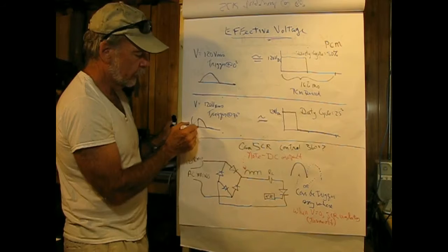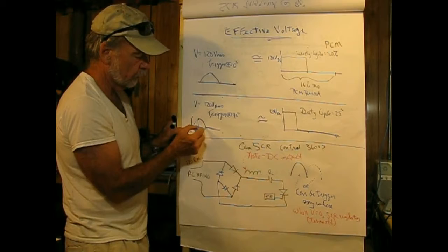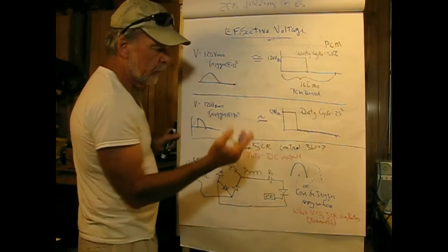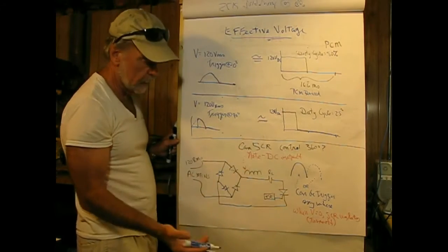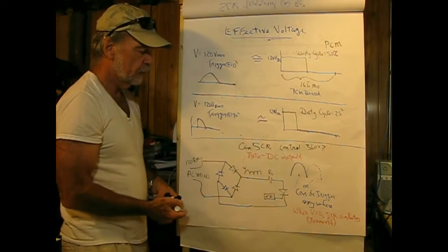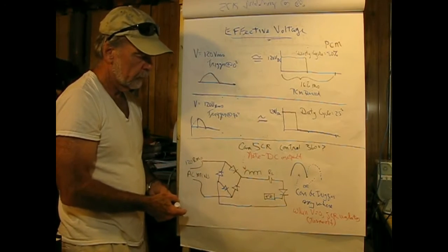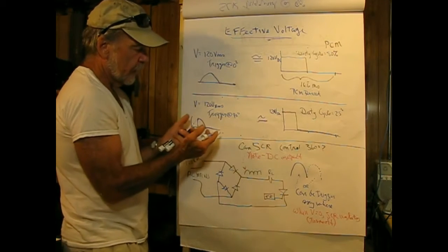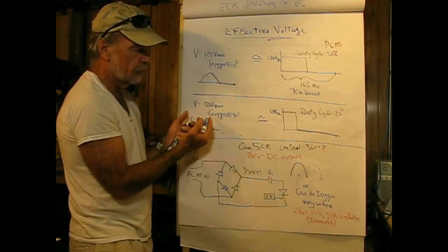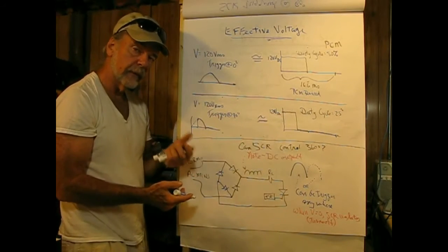It would trigger at 90 degrees and then jump up to about 170 and then follow the cycle through to 180 degrees, and that would correspond to PWM, 120 volts DC, again, with a 25% duty cycle. And if we did the math on this, we'd find the voltage would be about 85 volts effective. So if in our mind's eye, we can relate the operation of an SCR to pulse width modulation, we can kind of get a handle on the way the thing works.